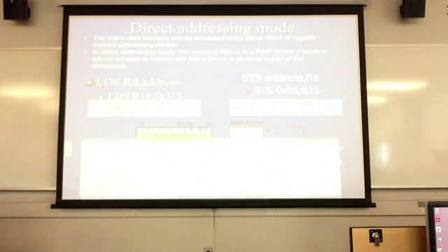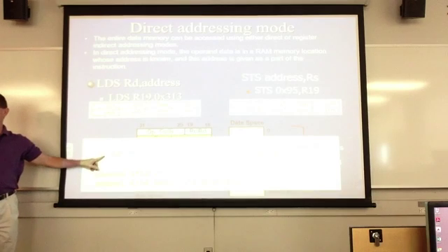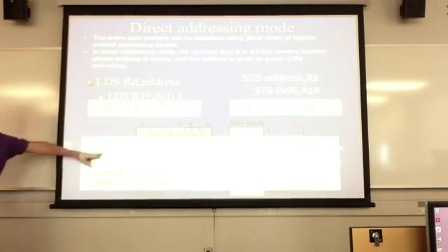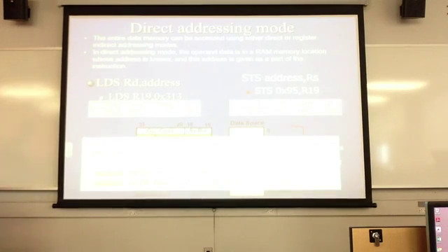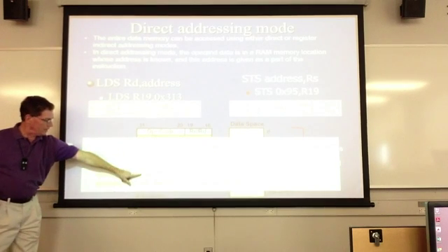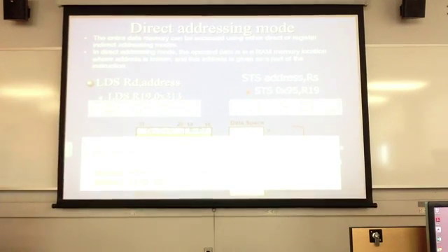Let's see. I actually went into the LSS file for this, and here you can see it. What we were doing is register R19, and when I have 19 followed by a D, sometimes I will put a subscript 10. That means base 10, where D is for decimal. If it's followed by an H, it would be hex. Followed by a B, it would be binary. So 19 decimal comes out to be 10011. You lop off that part, I'm left with the 3, and the 3 is right there. That's just how to read the opcode for it.